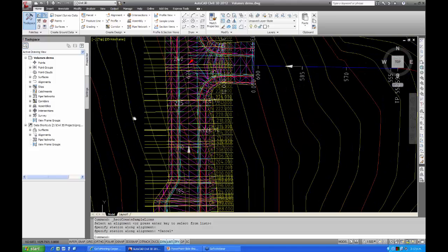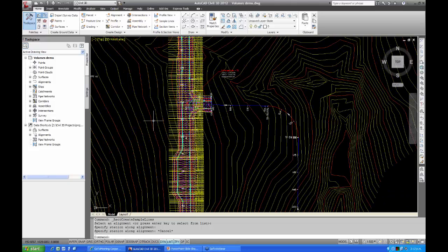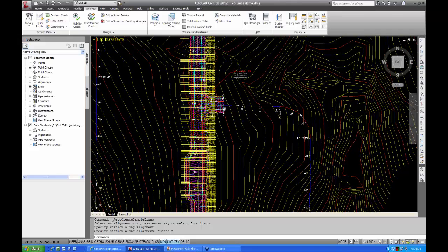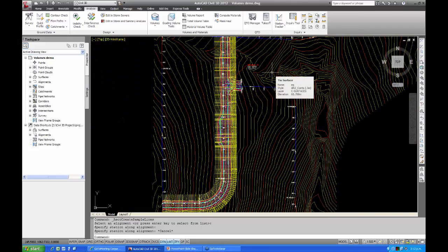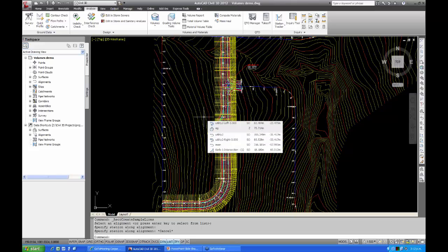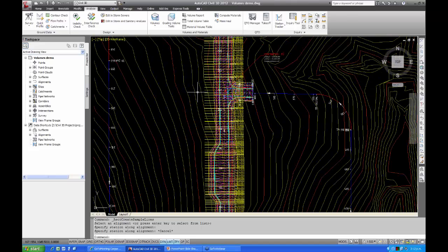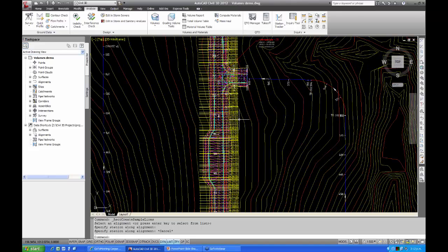Now, with that being done, we can then switch back to our Analyze tab, and we can start this calculation. The first one I'm going to do is just compare, well, the earthworks calculation, if you like, compare two surfaces together. So let's go and do that first. By the way, just before I go and do that, if you ever need to turn off these sample lines, or you don't want to see them in your drawing, often you don't once you've done this calculation, just turn them off by layer is the easiest way to get rid of those. See sample lines, I think, is the layer.